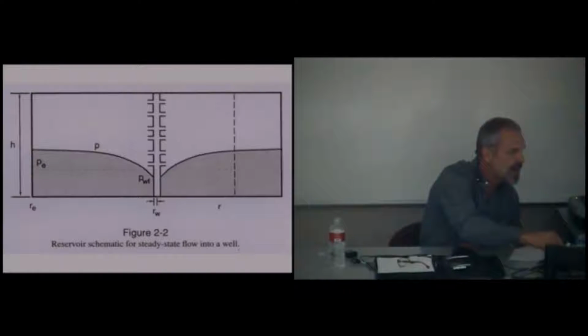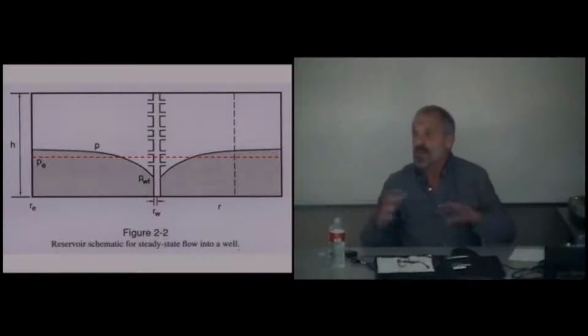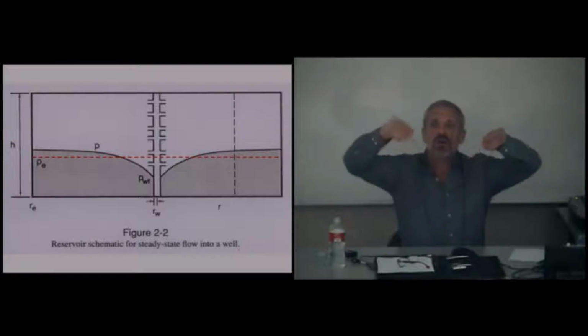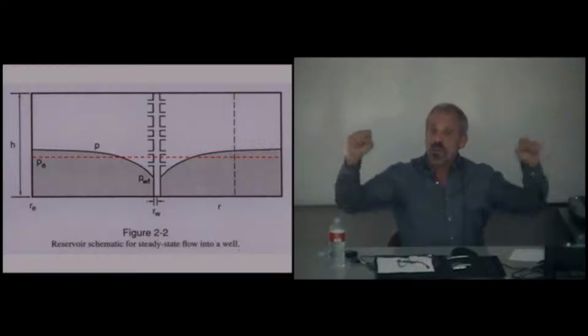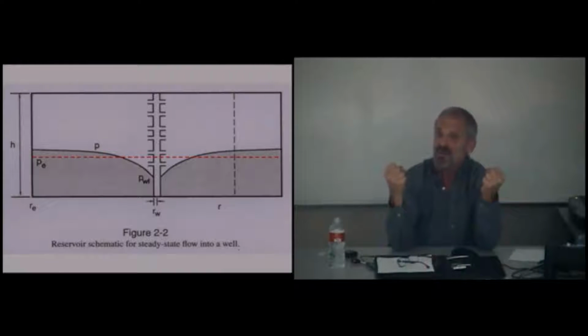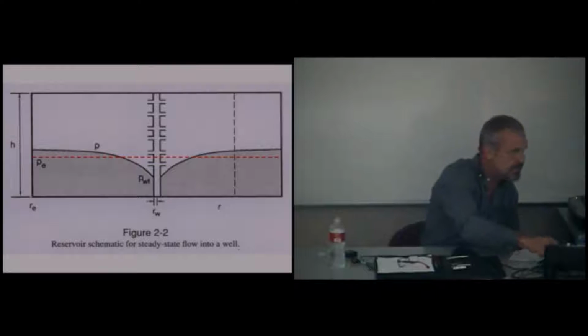And that bottom hole flowing pressure, which you can see is PWF on this graph, isn't the abandonment pressure at all, because there's a cone that moves out. So the average reservoir pressure is lower than that abandonment flowing pressure. Okay? But we can get close to these numbers through different techniques.